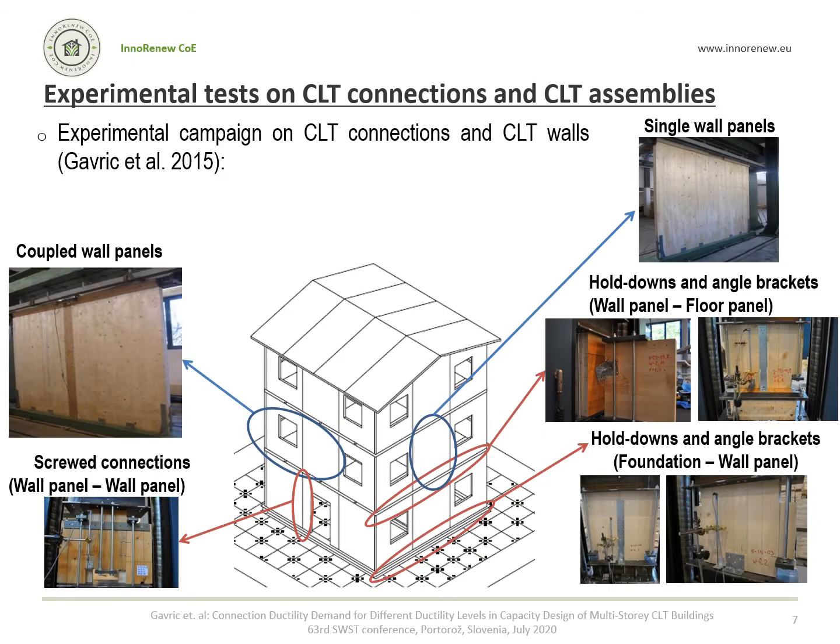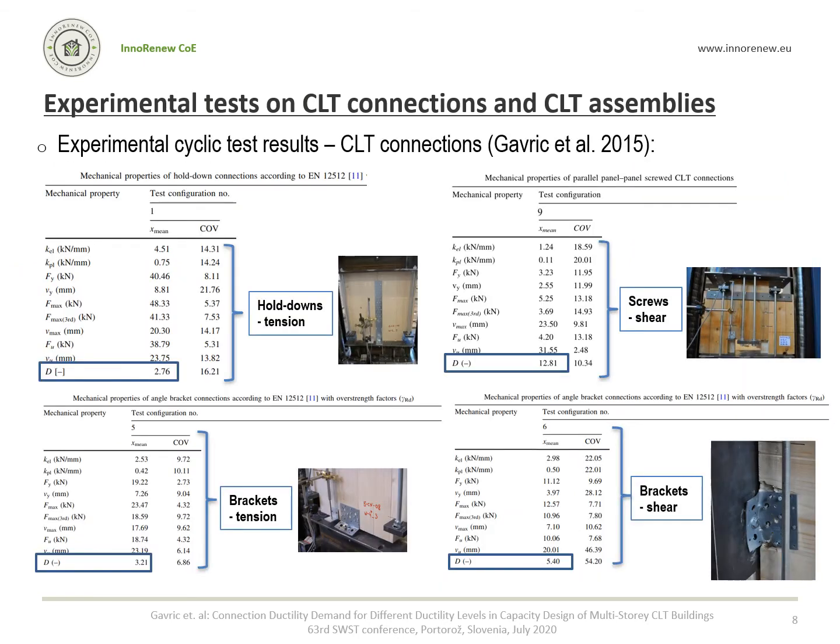We based our study on a previously done experimental campaign on cyclic behavior of CLT connections and CLT wall systems. Typical connections in CLT buildings were systematically identified and each of them was tested in all directions. We extracted connection ductility values, which were then used in numerical modeling.